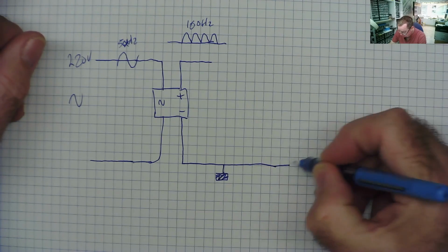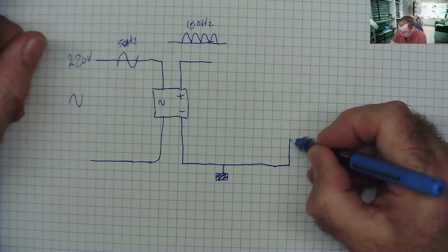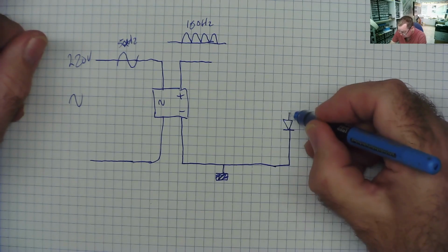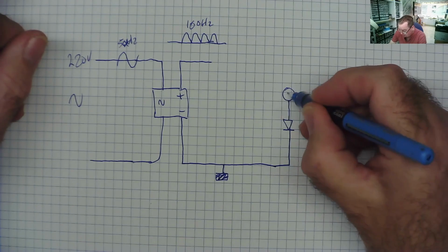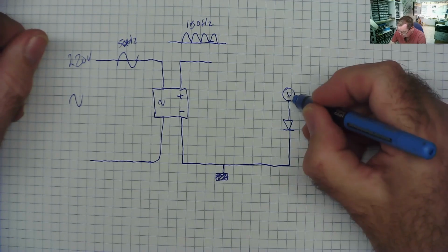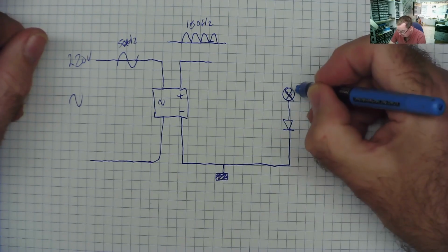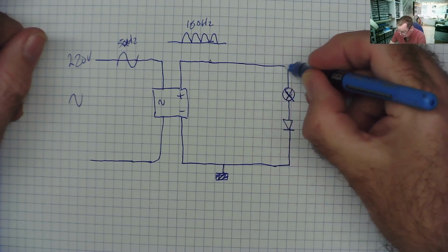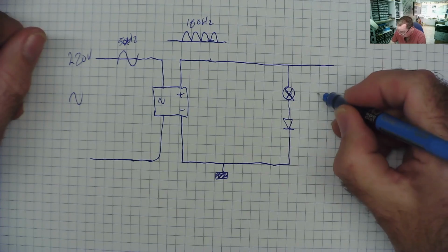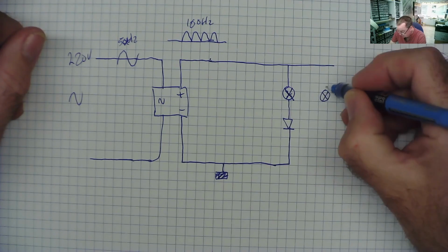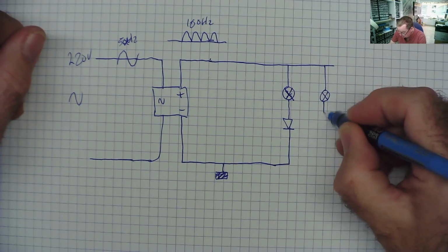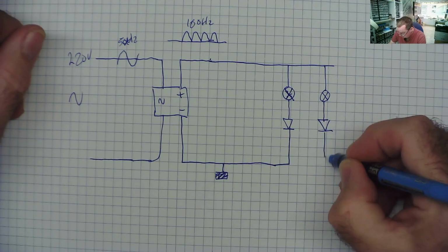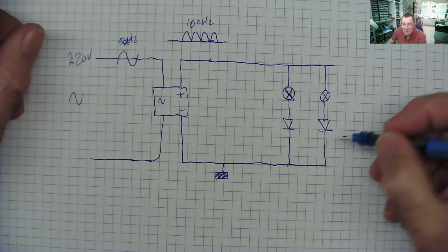We then have, on ours, 2 thyristors, one like so, and this goes to one of the loads, which is a string of LEDs. And the other end of this goes to the other end of the bridge rectifier. And we have another one, exactly the same thing. Load, which is another string of LEDs. The other thyristor. Hot ground. And we have a controller.